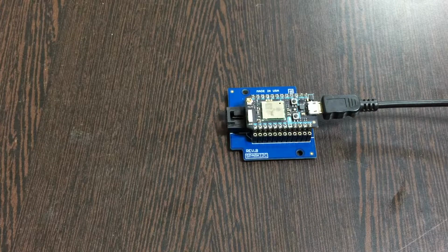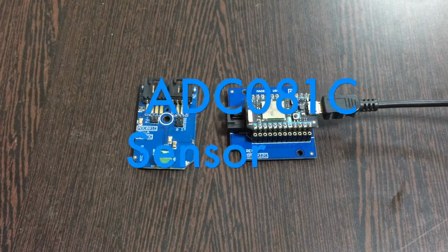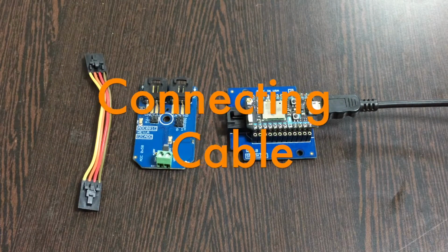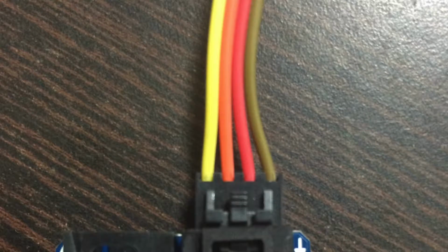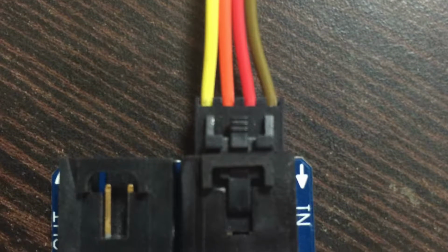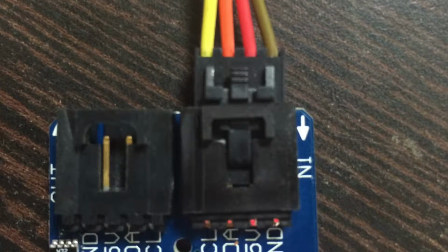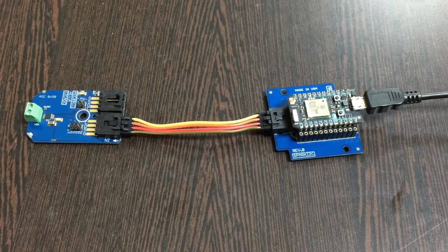Now next we require our sensor, that is ADC081C, and this here is our connecting cable. Now to make a connection between the sensor and the cable, we make sure that the ground terminal of the sensor is connected to the brown wire of the cable, and similarly this rule has to be applied to the I2C Shield. So as we are done with the connections part, now we need the explanation of the code. So let's have it.